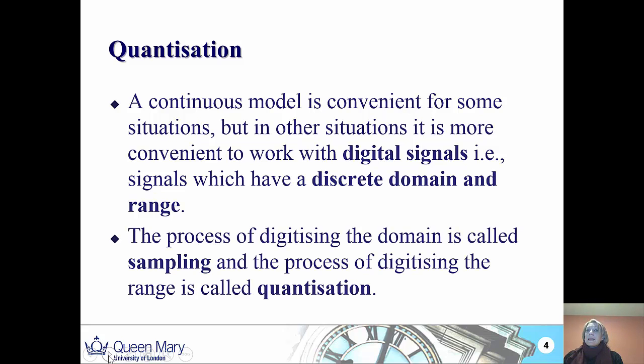So quantization is the next step after we sample our continuous signal. So we sample our continuous signal at least twice the maximum frequency of the signal. And the next step in the conversion of the signal in order to be communicated is quantization. So we actually want to assign the discrete values to these samples which may be communicated.